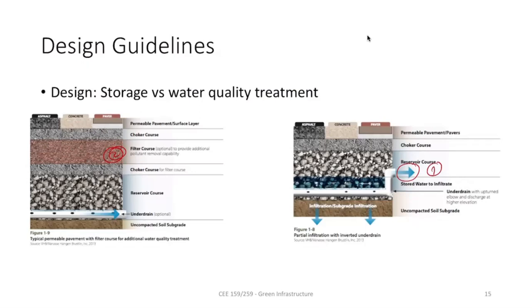Can you guess? This is the same design as in biofiltration systems or bioretention systems. What's the goal of the raised outlet? Is it to enable nitrification? It enables more infiltration into the ground because you create this head. So there is a ponding water height. Because you have lots of water, that pushes water much faster into the ground. So that allows high infiltration.